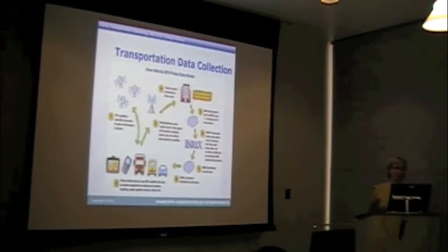After we run the model, we determine what the average daily traffic is right now in the valley. We then compare it with actual traffic counts, and that's how we know if the model is good or we need to go back and retweak it, making major or minor changes to make sure it reflects the actual traffic.